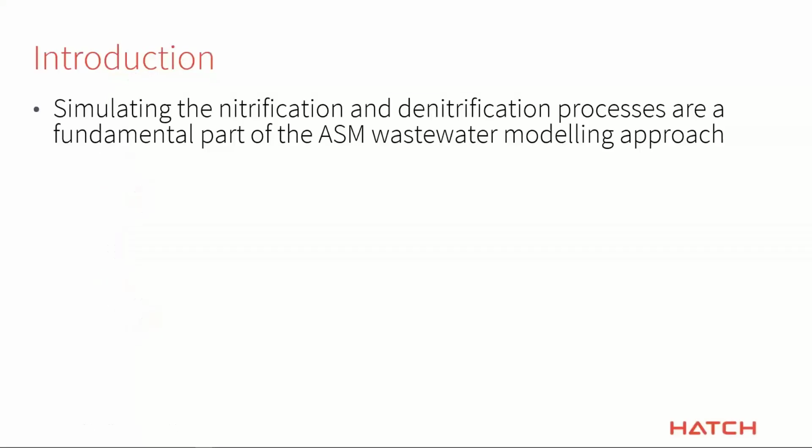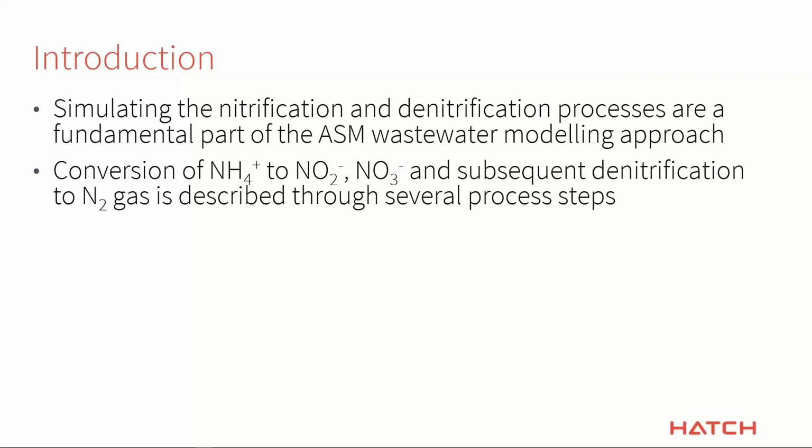Okay, moving on. Simulating the nitrification and denitrification process is really a fundamental part of the ASM type wastewater models that exist in our industry. It's been there right from the very beginning. Modeling nitrification and denitrification was part of ASM1, even though it was a slightly simpler approach back then. The conversion of ammonia to nitrite and then to nitrate and then subsequently denitrifying into gas is described through a series of several process steps. And we have a whole set of equations that kind of come to life under the appropriate circumstances and do the steps in that process.